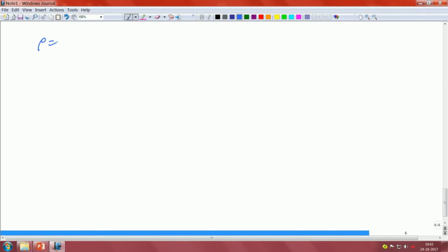Now let us see what the density will be. So, density is given by rho. If you take a first order expansion in this particular case, beta (T minus T infinity) plus a lot of higher order terms. This essentially tells you that beta, if you recall, is nothing but 1 over rho d rho by dT at constant p.